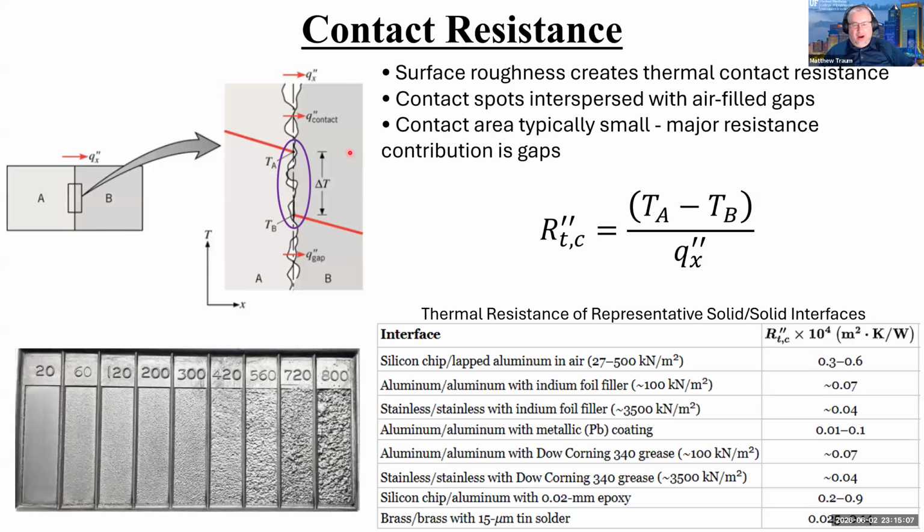And so therefore, in our resistance analogy that we've been talking about this whole time, it behaves like another resistance. What I want to point out, I've circled it here in purple to remember to talk about it: the thermal gradient is coming in. Here the temperature profile is linear, because it's one-dimensional conduction through a slab with no generation. So we've seen that before.